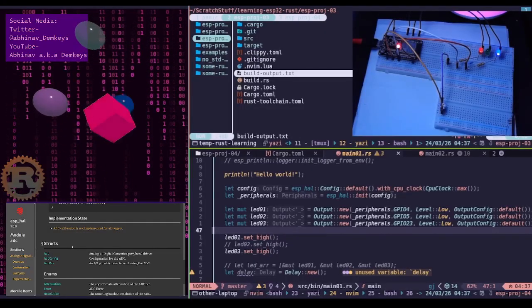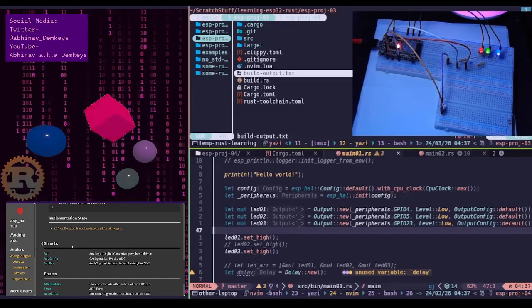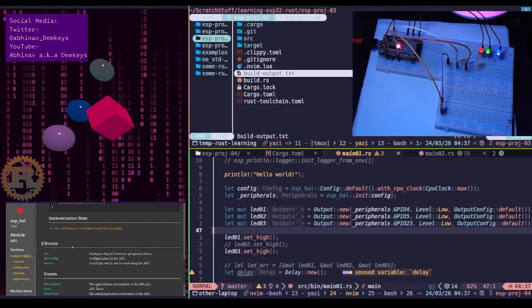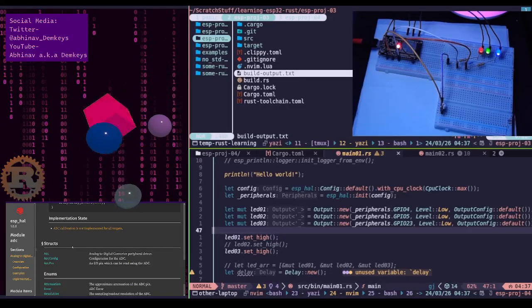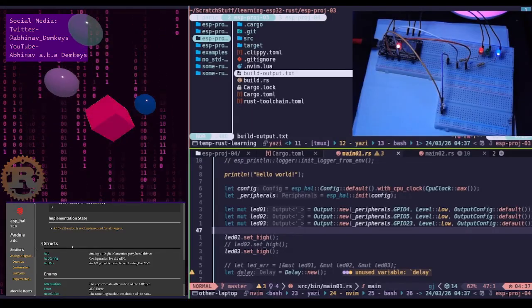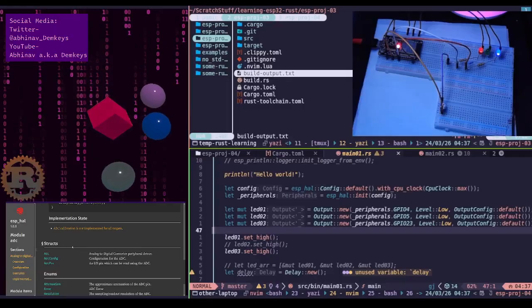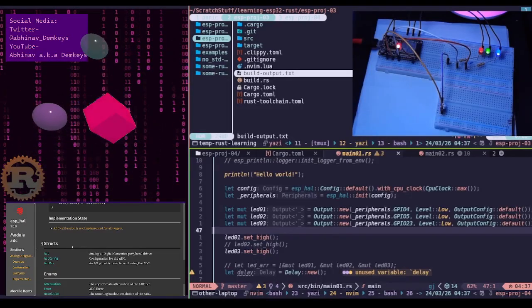This changes the total resistance of the bottom half, which messes up the math and drops the voltage further than you intended. The golden rule: use voltage dividers to tell a microcontroller what a knob position is. Use PWM or a dedicated regulator to actually change the power going to a component.